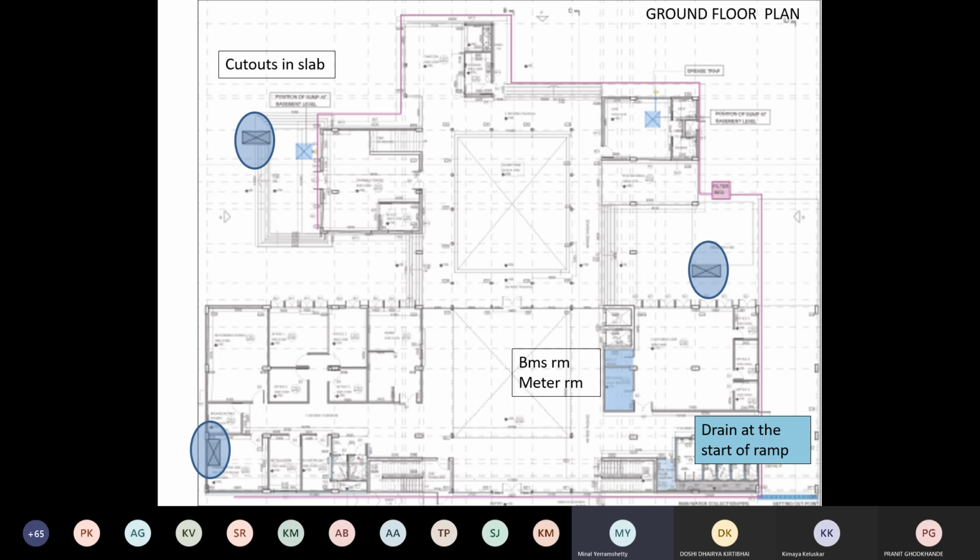And then, I don't know whether it is possible to zoom, but do you see a yellow dot on the right-hand side, the same blue color box with a yellow thing at the top? Can you see that? Yes. Right, that yellow thing is a grease trap. So what she's doing is, in the basement you have the drain pattern. From the drain, she's collecting to the sump, then with the help of the pump throwing the water out.